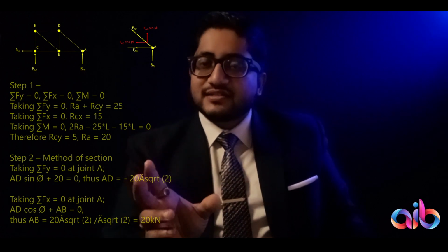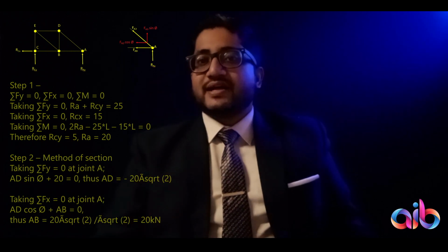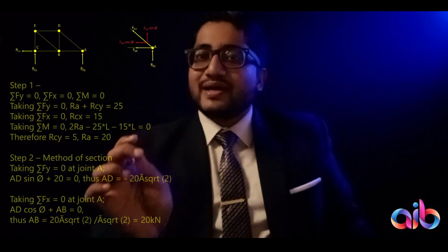So I'll consider this a negative magnitude. So I will have a subtraction, and 25 is the magnitude, and the distance of this force from the point C is the distance of the line of action of the force, and not the point at which the force hits. If the line of action extends to infinity, the line of action is at a distance of 1 times L. That is why I have considered 25 into L.